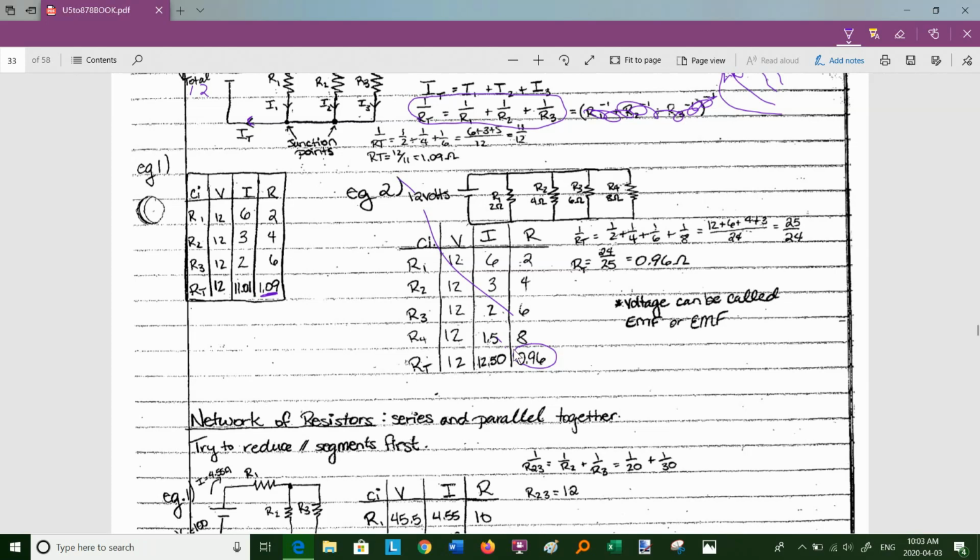Have them on their own dedicated circuit, and don't use an extension cord either, or a power bar. That's bad news. So those portable heaters have to be treated with respect, because they draw lots of current. So if you hooked up 3 in parallel, you're asking for big time trouble. And hopefully there'll be safety switches, but not all of them have these safety switches.